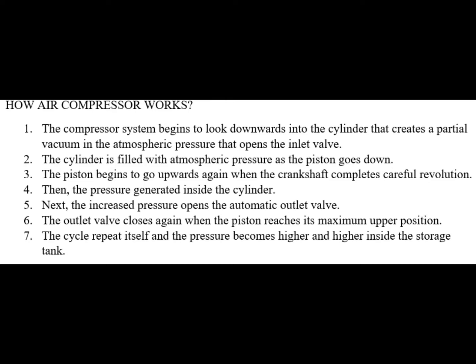Then pressure is generated inside the cylinder. Next, the increased pressure opens the automatic outlet valve. Next, the outlet valve closes again when the piston reaches its maximum upper position. And for the last one, the cycle repeats itself and the pressure becomes higher and higher inside the storage tank.